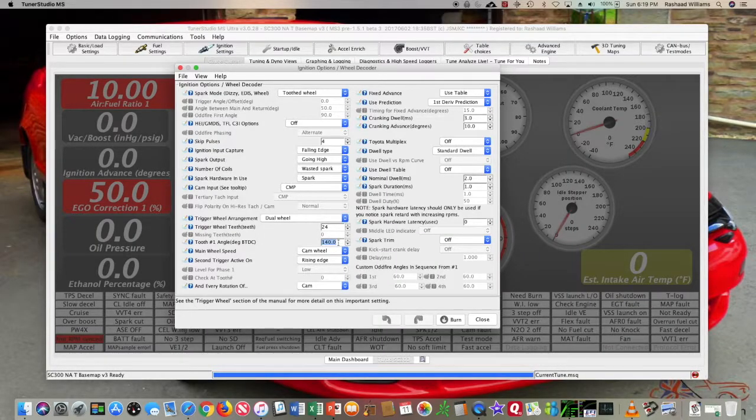So you need to have it set up to that. Having it set up to that, set up that number right, it's going to give you a rough guess of what this number needs to be. From there, I think mine came out a little low. The car would start, but then once you put a timing light on it, you can adjust it a couple degrees either way to get it dialed in just right. You will need a timing light to really get this number perfect.